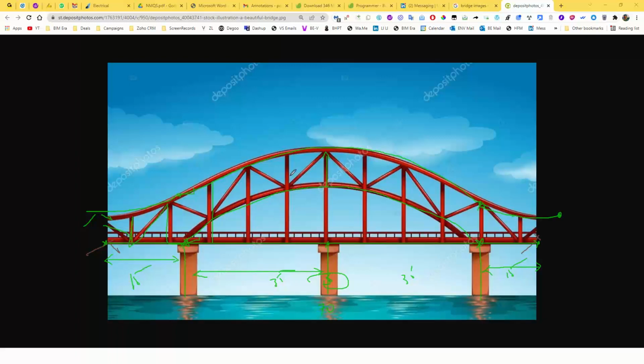Don't look at the complete structure at the same time. First, get all the vertical lines. How did I get that? I have a curve here, and I have one more curve here. So I need equal points. If I have 10 points here, I need 10 points on the curved shape also. So this point and this point will be connected, and this point and this point will be connected.